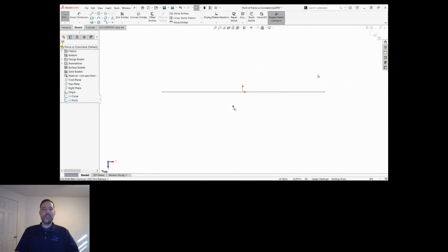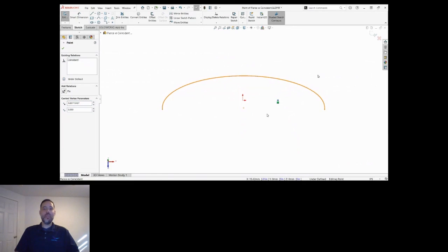So I'm going to edit the sketch of the point, click on it, click on the curve, and then I see Make Coincident. Oh, it's touching, right? However, when I move it back and forth, I can still move it. It's actually coincident or touching the projection of that curve. So I'm going to get rid of that.